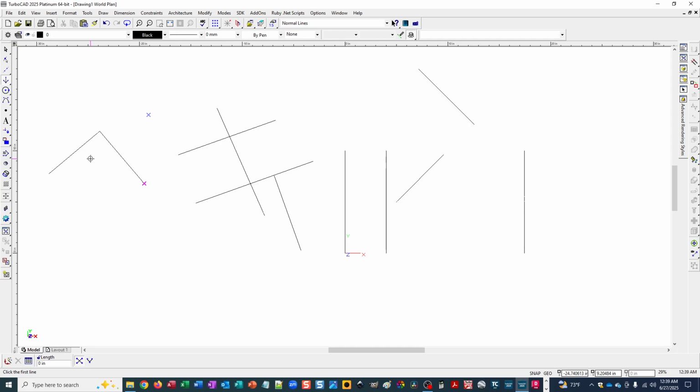And then it will calculate and reference, like in this case, the point of the V formation, but it's going to draw a line that is directly halfway between those lines, if that makes any sense. So I'm going to reference my first line, and then I'm going to reference my second line, and then it asks me to select a third point, and I'm just going to click inside this V here.